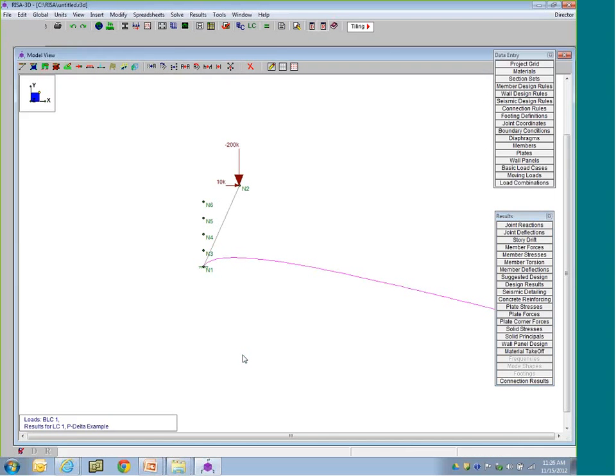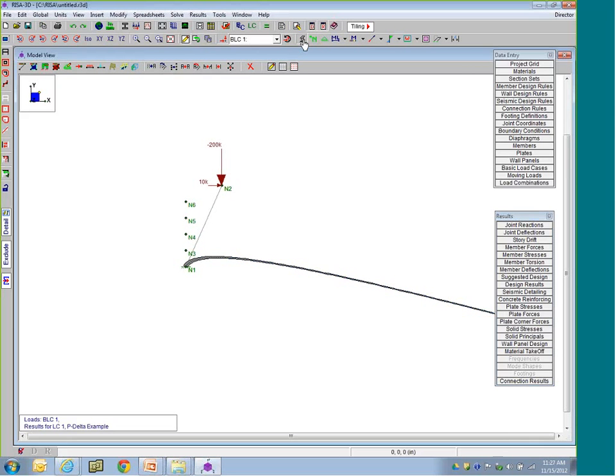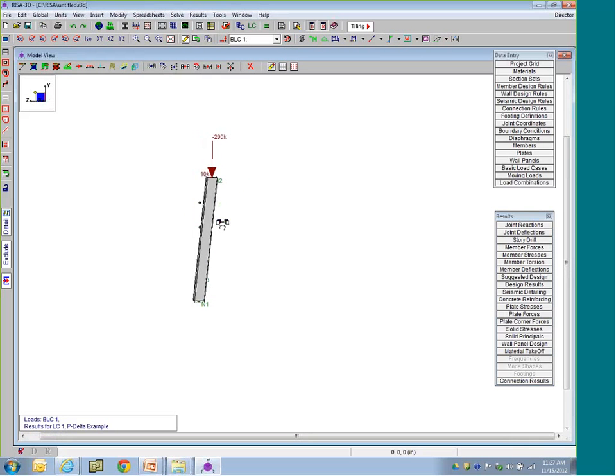So really there's no resistance. It doesn't matter what happens. That column is not stiff enough in that direction. In order to get that column to be stiff enough, first of all, it's in its weak axis, so maybe rotate it, or if we can't rotate it, maybe upsize it so it can resist that. But that's the classic case of why can't my model run, why am I getting a divergence? So we see exactly what happens in that model.